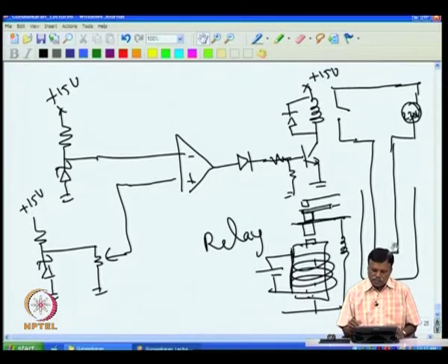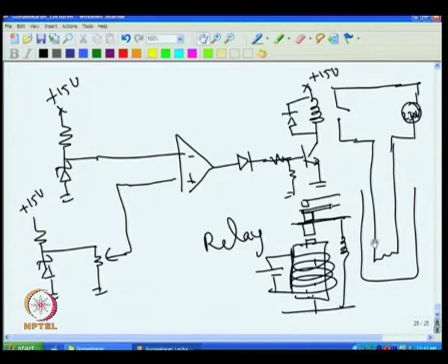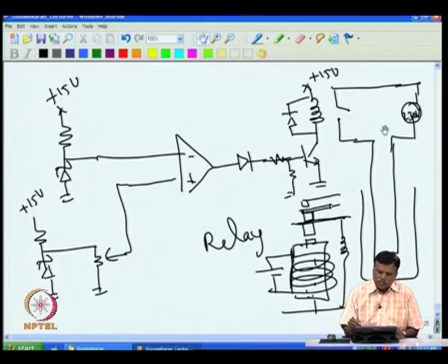For power, for example, this need not be even a heater, this can be a motor, wherein I am using position control. Then I have to switch on the motor if it is below the desired position, and when it reaches the actual position I will switch off. So, I do this using a relay; it can be easily done rather than driving the motor, which has its own complications. Of course, the speed you get through relay operation is limited, and there is also the noise. That is why the relay is used.